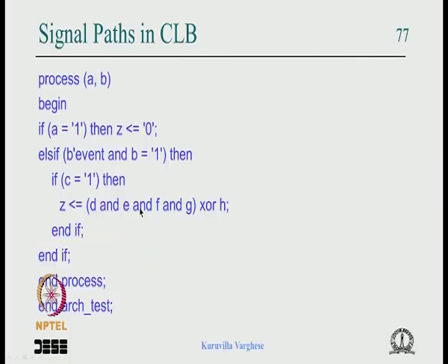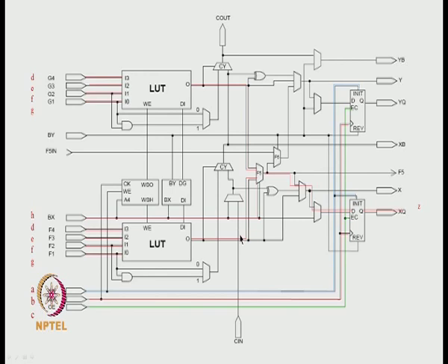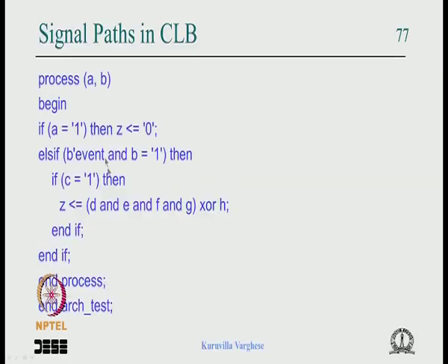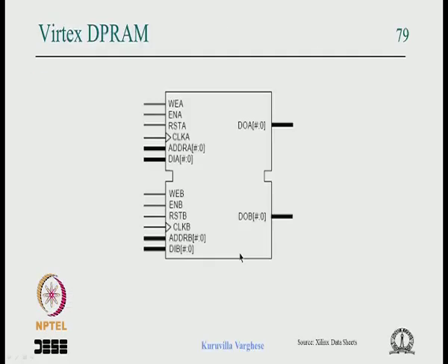So let us come back to the slide. That is how, given a VHDL code, it is mapped here. Definitely I skipped one step, I didn't draw the block schematic which the synthesis tool synthesizes. You can do that because it's fairly simple, that's why I didn't draw it. So that's how things happen, and the Virtex has block memory built in. The Virtex FPGA has dedicated memory built in, which, if you want to use, you should not write the VHDL code for it.